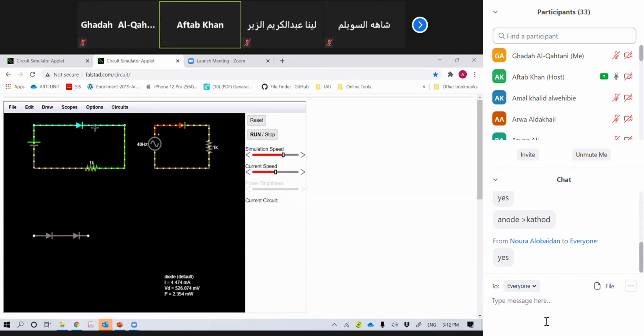Do you remember this practical model? The practical model considers that this diode will not only be in forward bias, and will not behave like a switch, but it will also consume 0.7 volt across it. Then only it will be in forward bias. So if I ask you how much will be the voltage across this resistance, what should be your reply? Voltage across the 1 kilo ohm resistance. How will I calculate this?